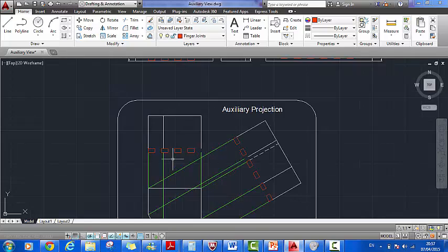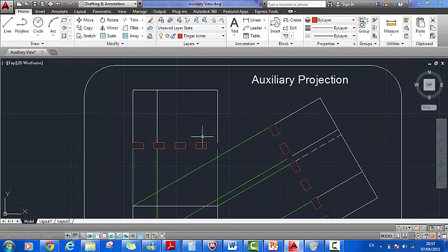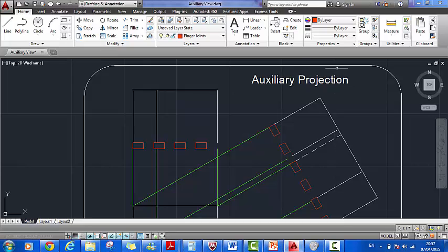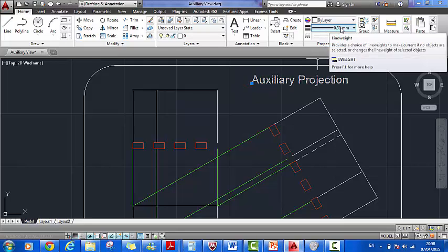Now, if I zoom in, we can see that these orange rectangles here are for the finger joints where our elevation plane and our true shape plane slot into. As you can see up here, they're also zero thickness. They're going to be cut out. It's a vector cut. One last thing to show there is our text. We also want this to be engraved and not vector cut. We can see that this is also a thickness of 0.3 millimeters.